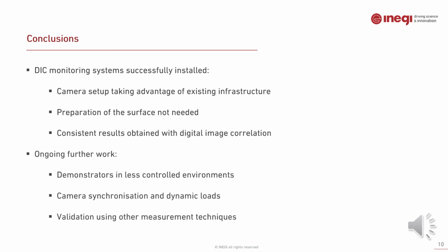And some further work, which in the meantime is under an advanced stage of development, includes demonstrators in less controlled environments with, for instance, natural loading caused by passing vehicles instead of a load controlled by us. Better synchronization of the stereo camera system in order to evaluate dynamic loads, and validation of our DIC method using other techniques such as sensors installed on the structure.